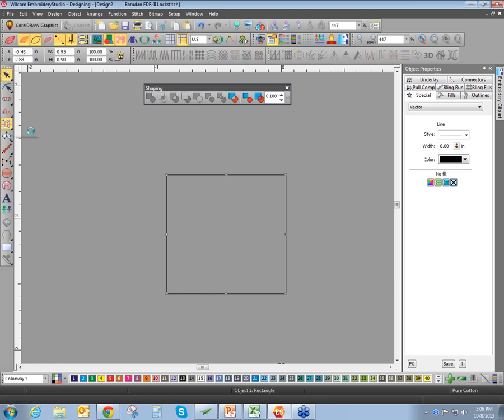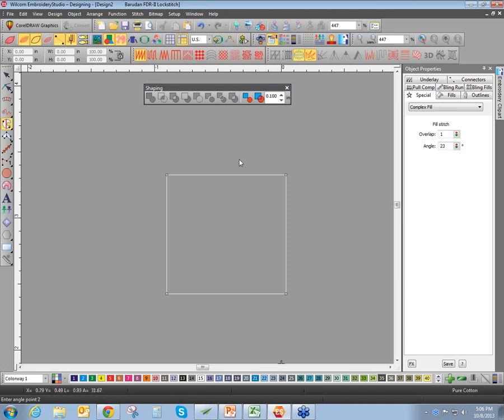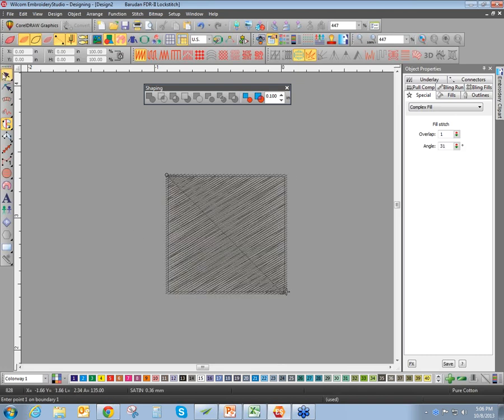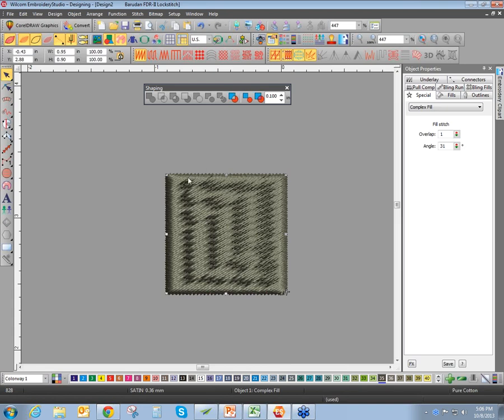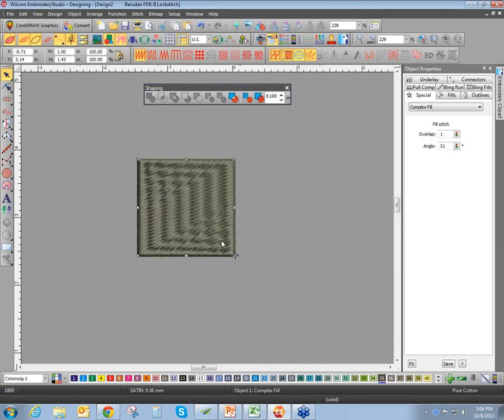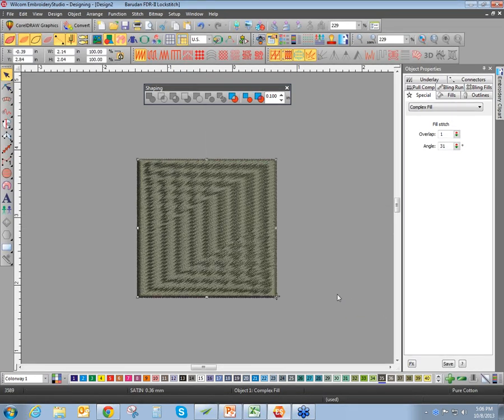I can convert any of these objects into a stitch file. So click of a button, I want to make that a fill stitch. I can do that. Done. I'm going to make a checkerboard to highlight and show the smart branching feature. So again, in doing that, we're going to do drawing tools. Instead of doing a run stitch, I'm going to do a vector poly line to create a separation of fields, if you will.